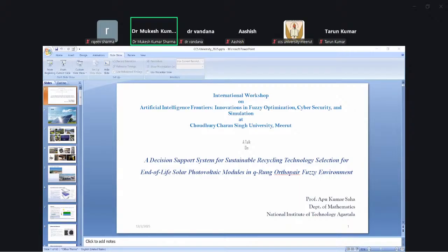Then the third type is thin film solar cells. Thin film solar cells are made up of a variety of materials like amorphous silicon, cadmium telluride, copper indium gallium selenide, etc. As the name indicates, thin film solar cells are often slimmer than the other two types, monocrystalline and polycrystalline. The manufacturers place a layer of CdTe, that is cadmium telluride, between transparent conducting layers to help capture sunlight, so that maximum sunlight can be captured.